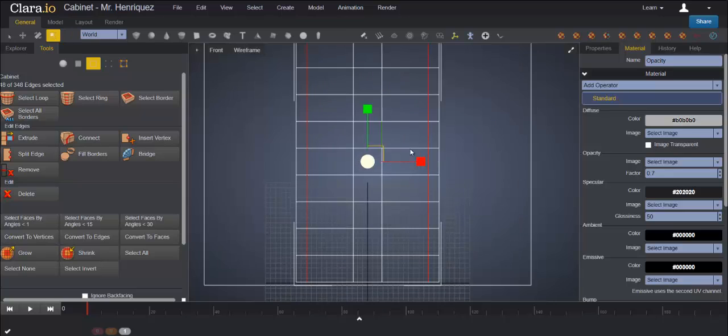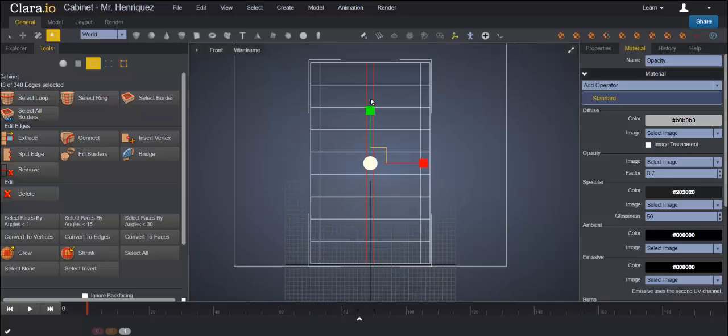And just, once you're satisfied with the width on each side, then stop dragging, and let's do the same thing for the ones in the middle. So let's just double click to select one, and then hold down Control key, double click again, and then just push in. And again, once you're satisfied with the width, you let go. And again, I'm trying to create all the dividers that the cabinet has. I'm going to continue rearranging the edge loops.